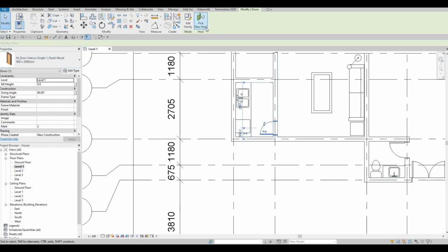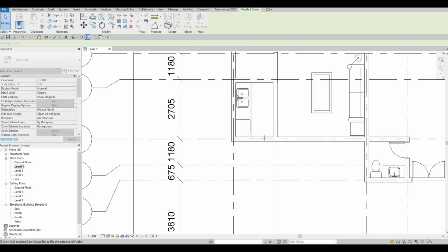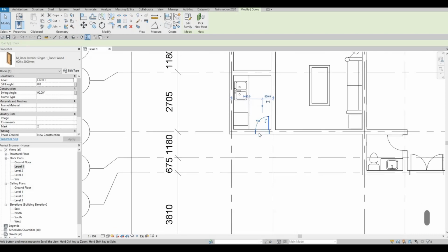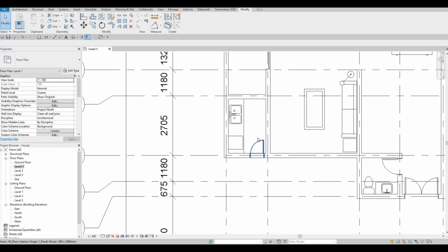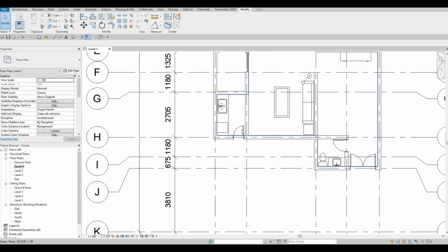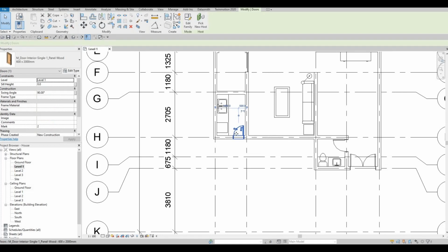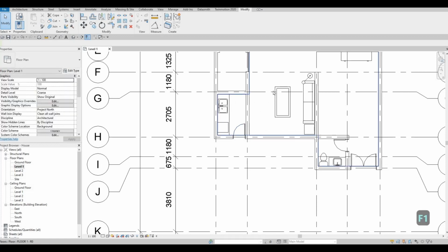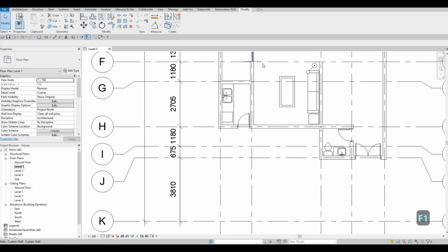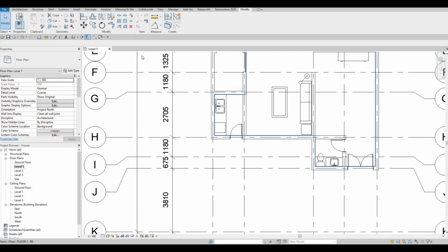So what you do in order to relocate this is to pick new host and then press spacebar to change orientation, and then just select this area. So that's how easy it is to relocate the location of the door. So here instead of 600, I'm gonna go to the drop down and make it 700 as well, similar to this, because we have enough space now in order to access this. Now what I want to do is to add the entertainment system all the way right here.